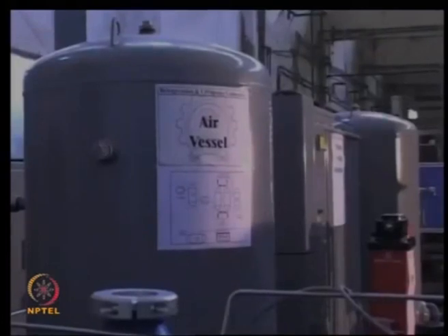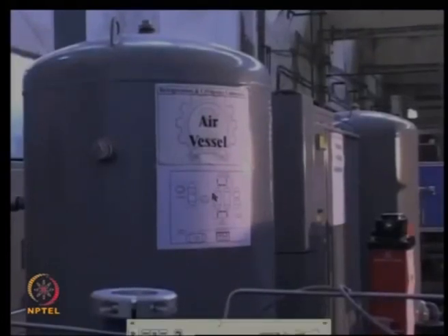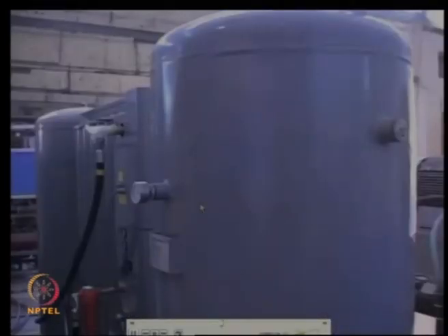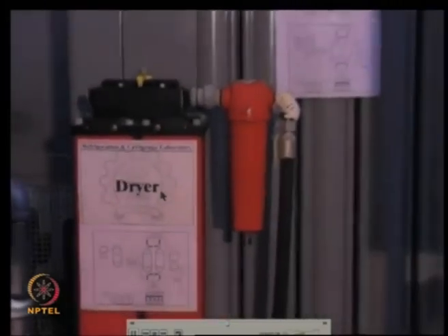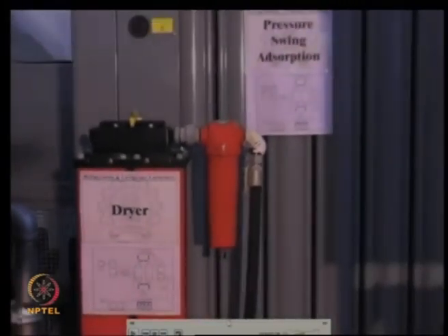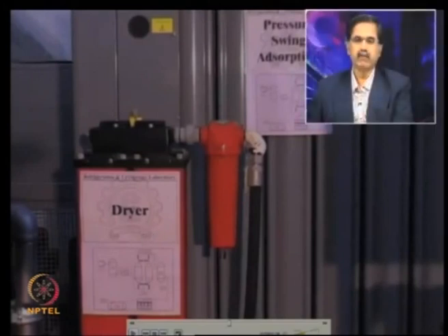So, once the air gets compressed to around 8 bar, this air will be stored in this air vessel. You can see it here also in this small schematic over there. When the air is getting stored over there, the air then will be dried. That means whatever moisture is there will be taken care of. So, we want only dry air to go after that from the air buffer, and from that dry air, the air will go to the pressure swing adsorption device, this PSA system.